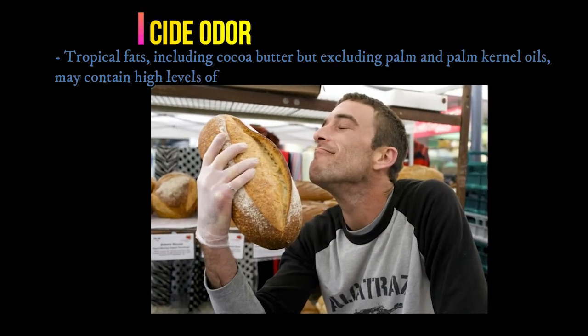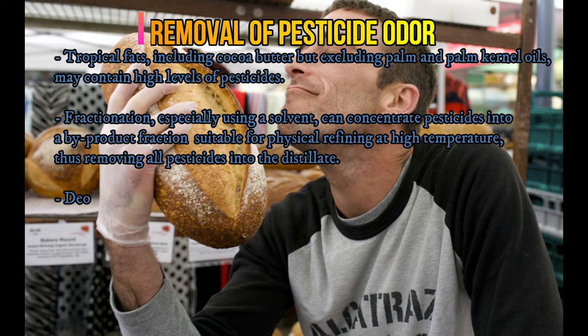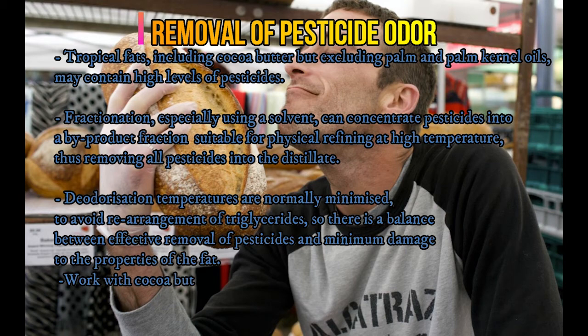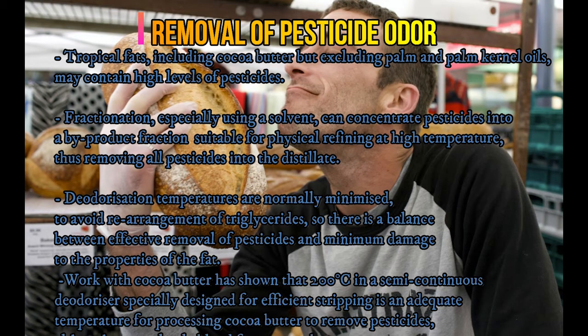Next, pesticides give an off flavor to the edible fats. Did you know that tropical fats may contain high levels of pesticides? Fractionation, especially using a solvent, can concentrate pesticides into a byproduct fraction suitable for physical refining at a high temperature, thus removing all pesticides into the distillate.